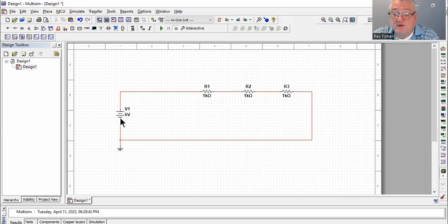Now, here's another thing that students sometimes have trouble with. They know that the charges flow out of the battery and they come through the resistors, and they come back here, and a lot of people have somehow been taught a myth, or they've been indoctrinated incorrectly, or I don't know what it is, but a lot of students think the current is going to go down to ground like it's a drain of some kind. Here's the water coming down, and it all goes slurping down here into ground. No, that doesn't happen. It's going to go back to where it came from.